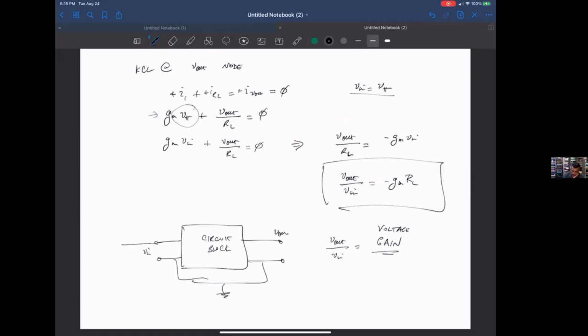So it's getting a real small signal, just because this mechanical membrane can't create a really large signal value coming out. And then you may just want to be able to adjust the loudness from the microphone. So what you want to do is put that signal into a circuit block that has gain, so you can amplify that.